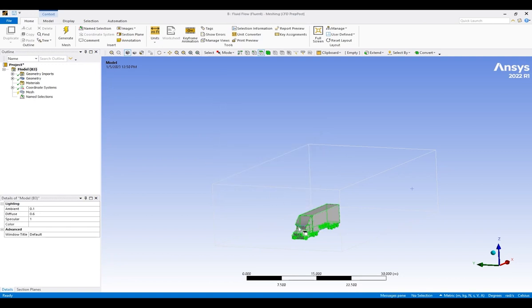Okay, now we can actually use this naming section in the ANSYS meshing itself, in the ANSYS meshing commands later, and that is the reason why we recommend that you define names for different surfaces of your geometry first before defining any mesh commands.